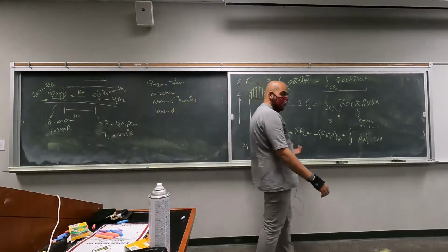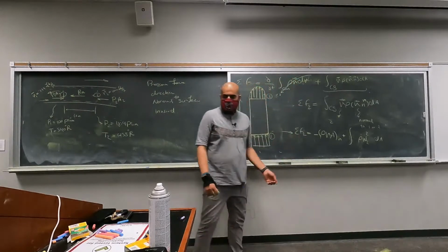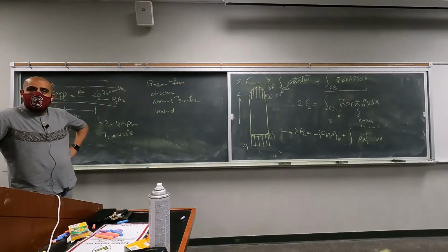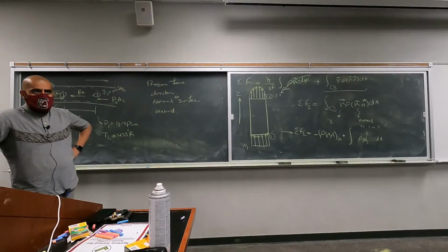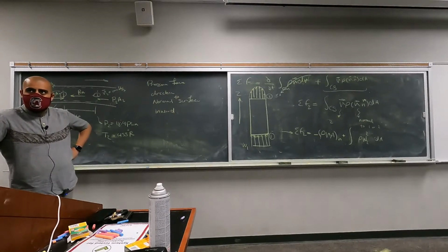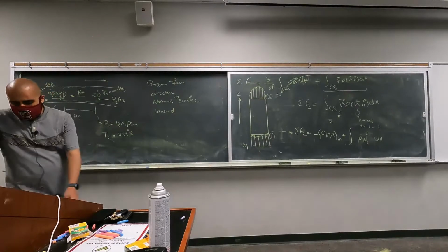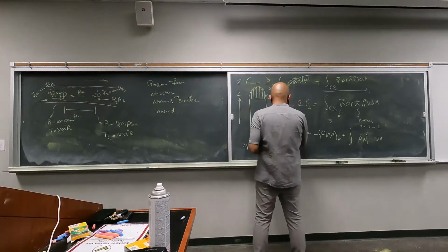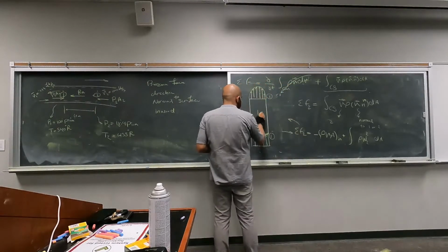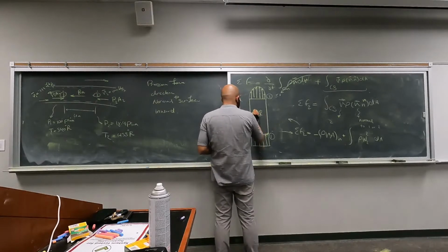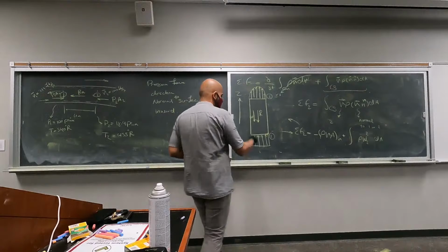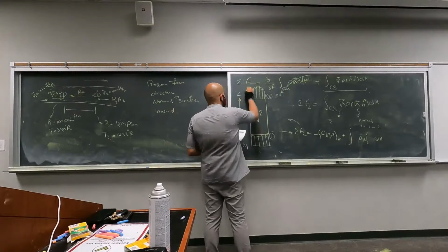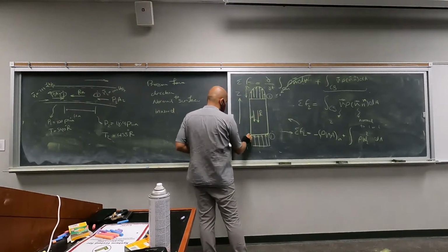Okay, let's talk about the sigma of forces. What are the forces that are present here? We are not told to neglect friction or gravitational force. So friction force is present, and also the gravitational force. Friction force is opposite to the flow. Gravitational force, or weight, is also opposite to the flow in this case. Pressure force is normal to the surface in the inward direction.